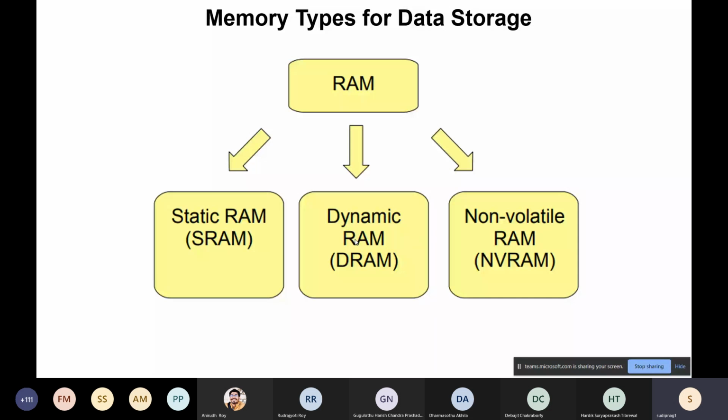And if you have a reduced space on chip, although these are in micrometer square or hundreds of nanometer square or even a few nanometer square, depending on the size of the technology, 180 nanometer or 7 nanometer, the size of DRAM per bit is extremely small as compared to SRAM.